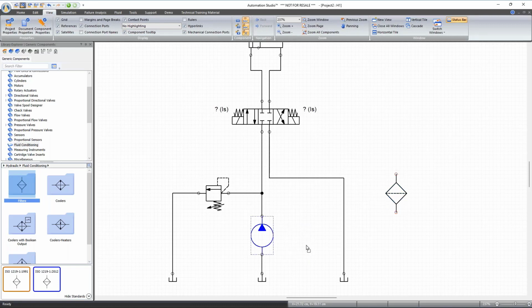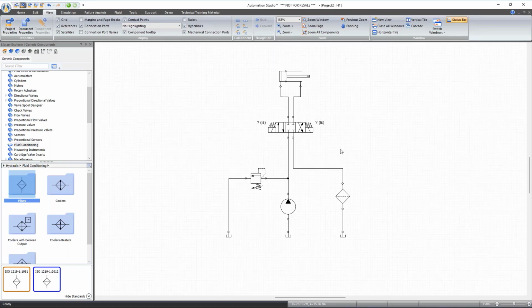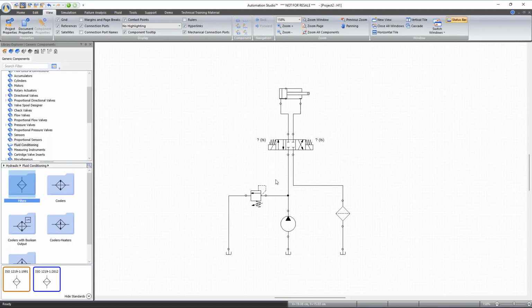If you do that with a pump, well, this may not happen. The line will not be rebuilt because the lines were built after the pumps were inserted. But easily you can bring another pump if you wish, the same way. So you don't need to erase the component, you only need to bring it in. And of course, in this case, this line will be broken into two lines with equal length and so on. Okay, so this is about the manipulation, the utilization of the Shift key to insert a component.